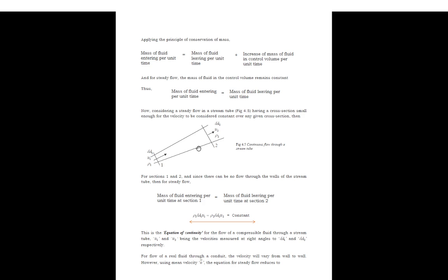And this is what is going to happen, is that all the time we shall look at our system from a perspective of two things. That if this was a pipe and we have continuity, and assume the pipe was the same cross-section area, and the fluid is the same, it means the velocity here and here would be the same, cross-section area would be the same, density would be the same. But assuming the pipe is tapered in this kind of form, is that we shall say that the mass of a fluid entering per unit time at section 1 is equal to what is leaving.